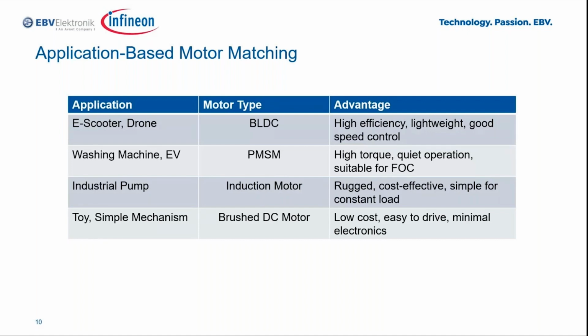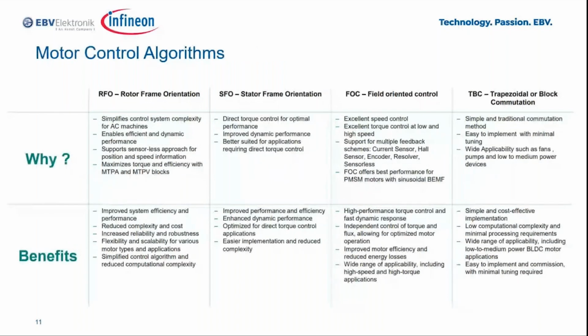And the next one, we can see the very big table from the Infineon side. In this table, we see the 4 different algorithms that Infineon supports for motor control. A quick look shows that RFO, rotor frame orientation, and SFO, stator frame orientation, are simple and specific versions of FOC, field-oriented control, used for a specific purpose.